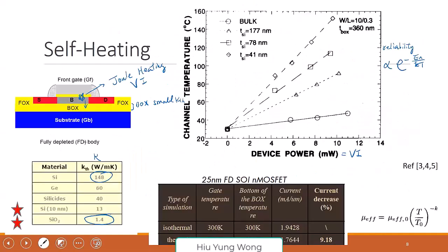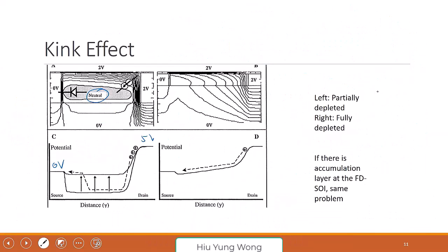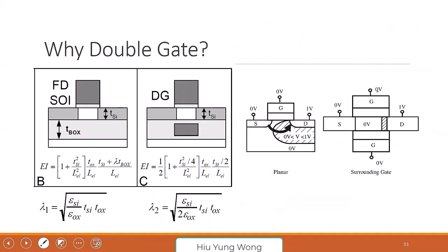Just like at the very beginning, we look at this graph. Hey, we just make VG1 and VG2 move in this direction. Then they go from both inversion to depletion to accumulation. A very strong control, right? So then we can do that, but now you realize that, hey, the oxide is too thick. I don't have enough power, right? So if the technology allows, why don't you have two gates, right?